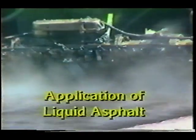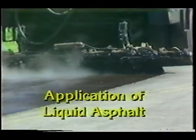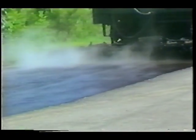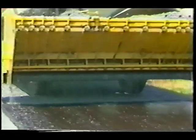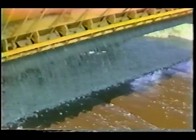The fourth step in this procedure is the application of liquid asphalt. The asphalt application is the most important part of a chip seal operation. Emulsified asphalt is recommended. However, cutbacks and asphalt cements can be used with good results. Select an emulsified asphalt based upon the compatibility of the emulsion and the aggregate.